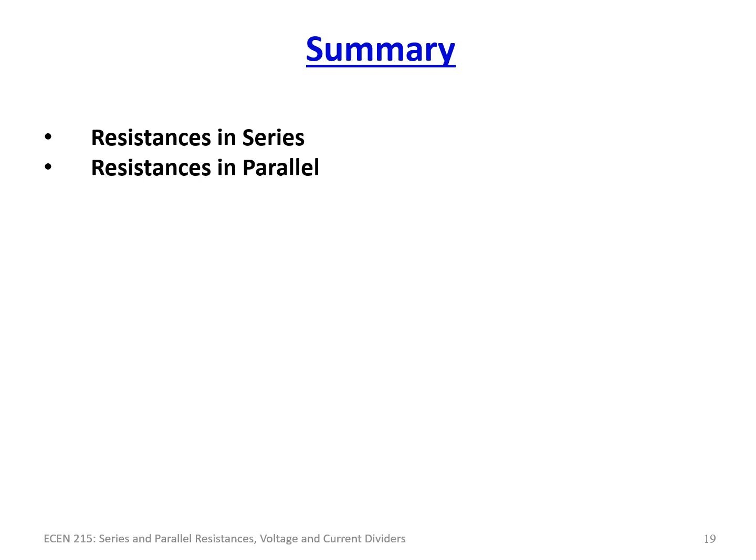In fact, you can use that in multiple combinations of resistors, and eventually we're going to learn something called impedance later in the class, which is very much like resistance, and it's going to be the same thing as applicable there. So again, resistors in series, you add up, and in parallel, it's just 1 over the reciprocal. So 1 over R1 plus 1 over R2 plus 1 over R3 up to 1 over Rn, where N is the number of resistors that you have.